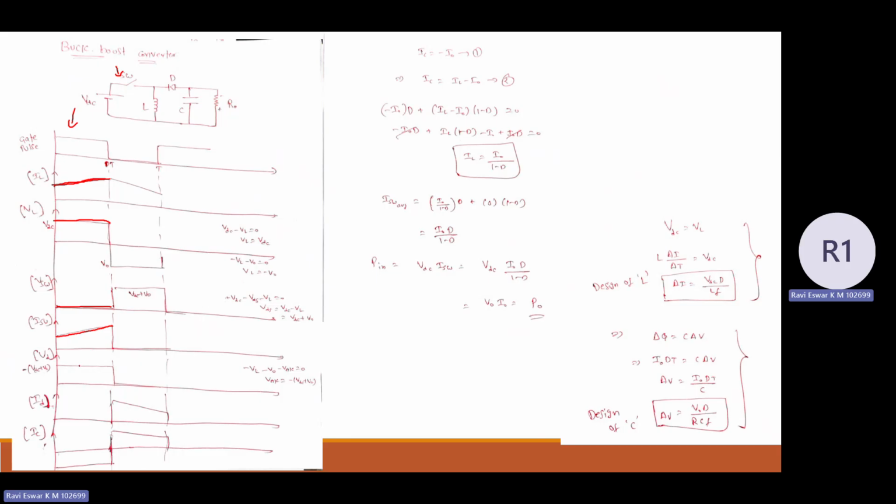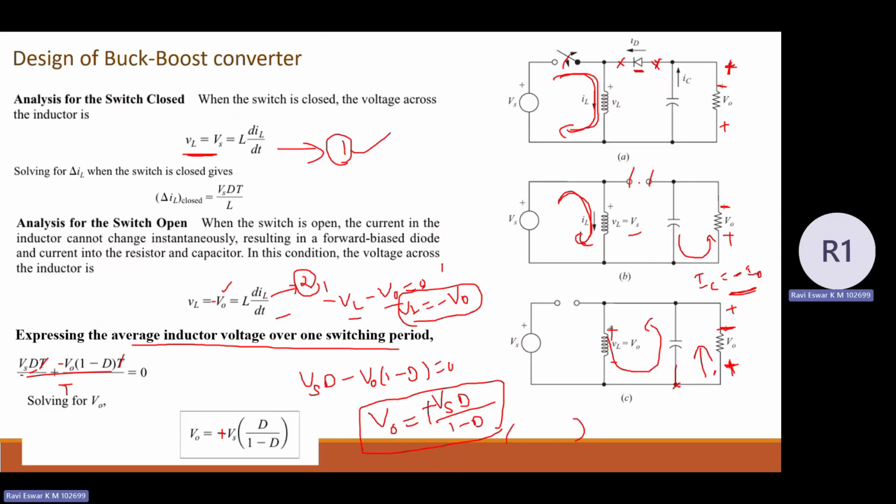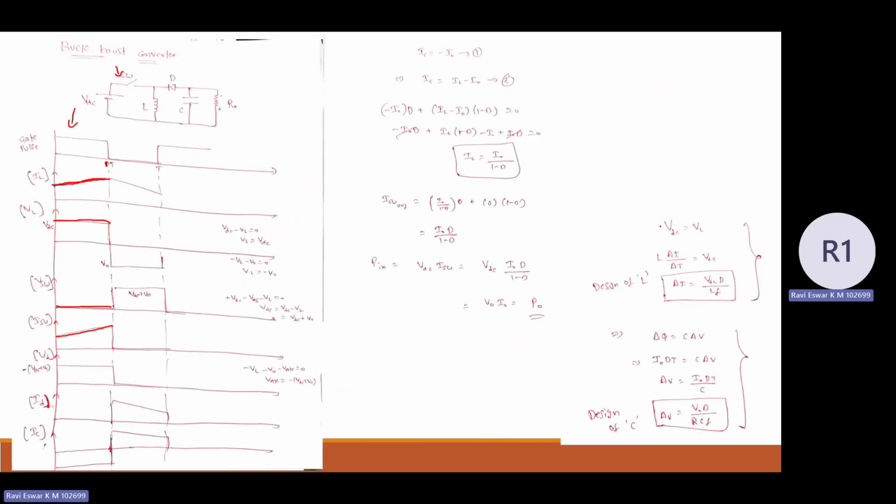Now what is the voltage across the diode? As I mentioned, the diode is going to be in reverse biasing mode. Let us prove why the diode is in reverse bias. For that, you apply KVL in this particular loop. Let me take here the anode, here the cathode, so here positive we consider as reference, here it is negative. Applying KVL in this loop, I can write minus VL minus V naught minus VAK equal to 0.